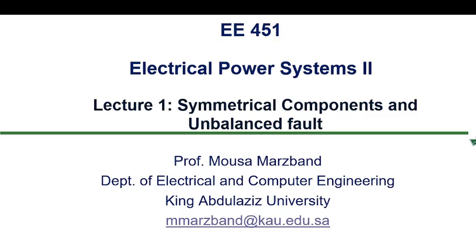And symmetrical components provide a powerful method to simplify these complex conditions by transforming unbalanced three-phase systems into three separate balanced sequence networks, including positive, negative, and zero sequences.